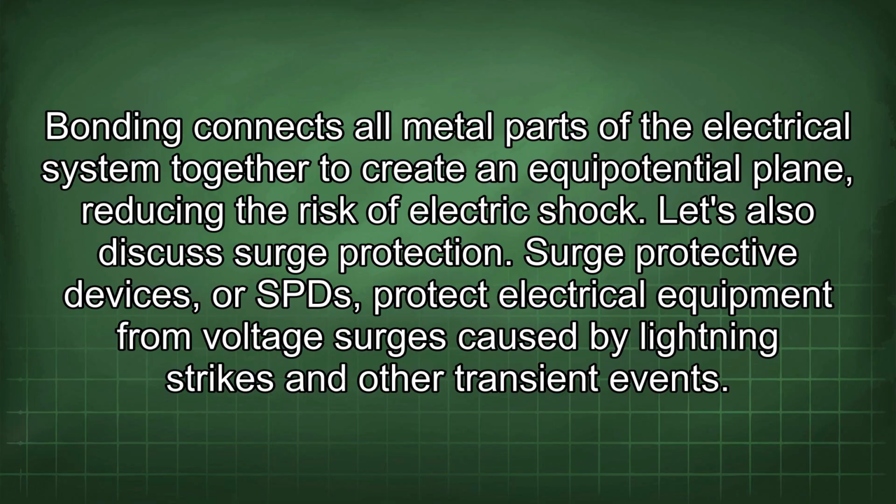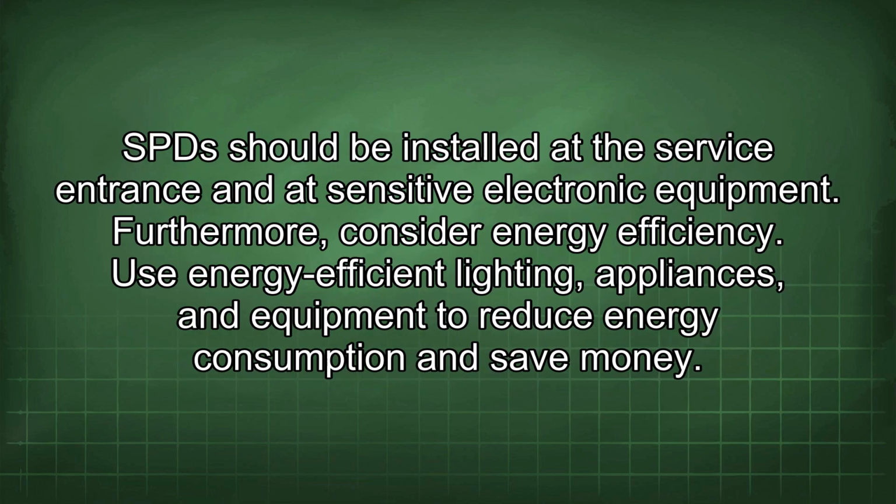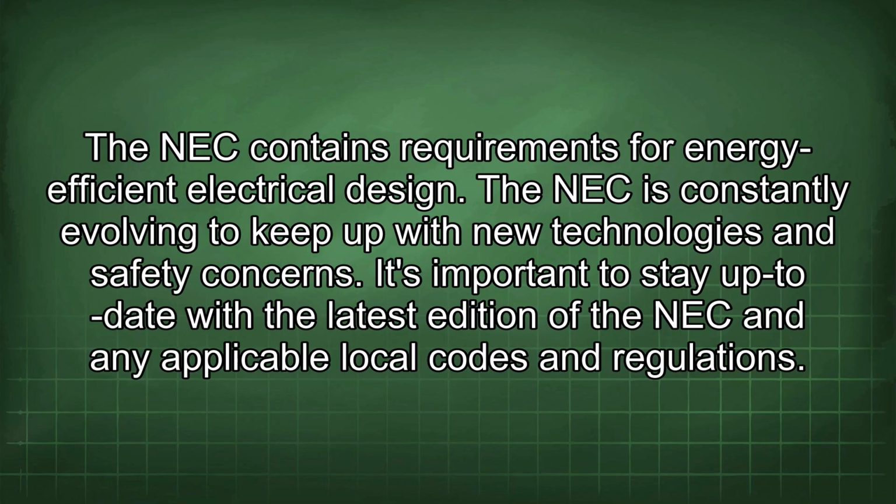Let's also discuss surge protection. Surge protective devices, or SPDs, protect electrical equipment from voltage surges caused by lightning strikes and other transient events. SPDs should be installed at the service entrance and at sensitive electronic equipment. Furthermore, consider energy efficiency. Use energy-efficient lighting, appliances, and equipment to reduce energy consumption and save money. The NEC contains requirements for energy-efficient electrical design.